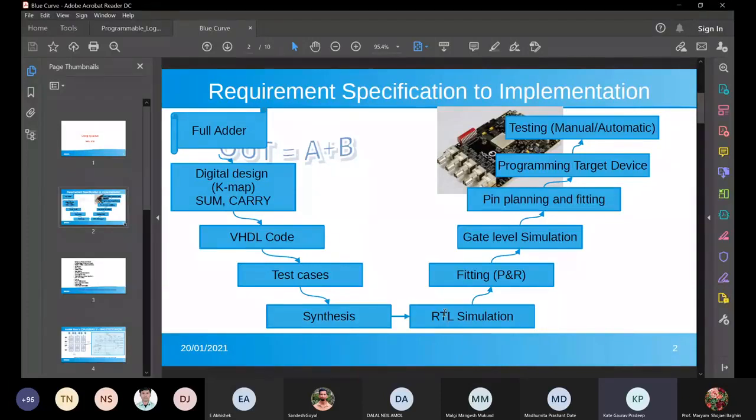That let's say the data is sent from the input and it is received at the output. We are just interested in the values and we don't consider the glitches, the delays, etc. So that is RTL simulation. You can also think of it like some ideal simulation where there is no glitch or there are no timing issues in it.